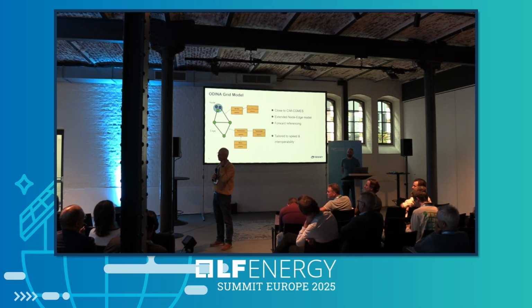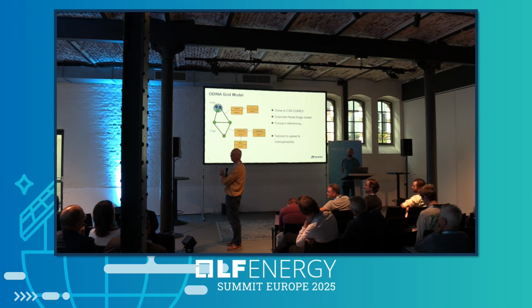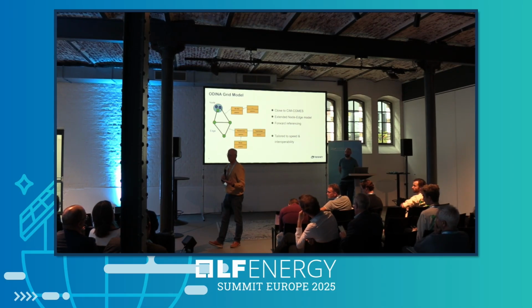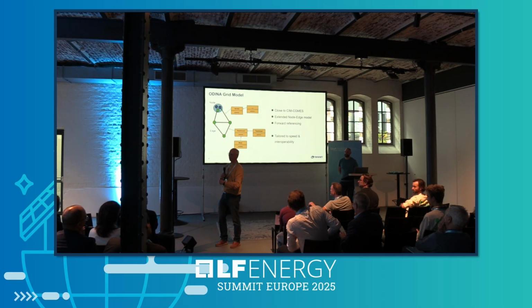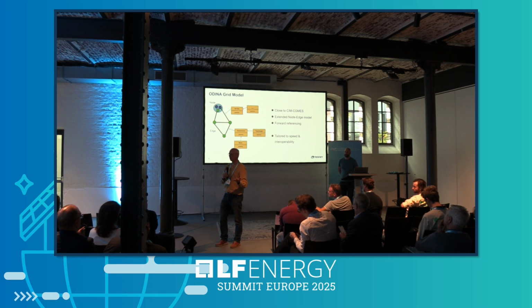No. This model is completely hidden inside ODINA. So we don't expect this. Nobody should use our ODINA model. This model is just internal to our toolbox. When you receive the data, we import well-known standard formats like CGMES, or maybe other ones in the future. We import PowerFactory models at the moment, but we do it through the API, so we just connect to PowerFactory and take all the data that we need. But we can also import UCTE format and PSS/E.